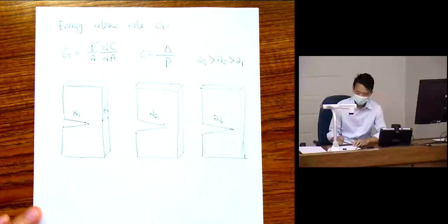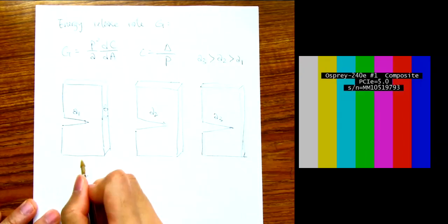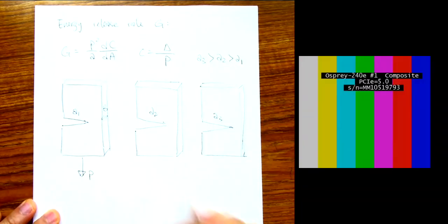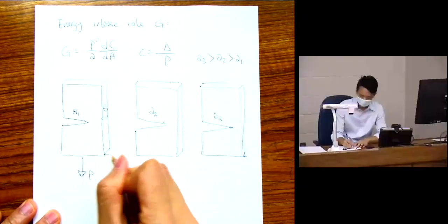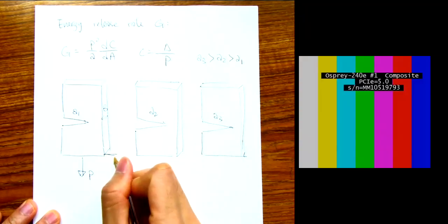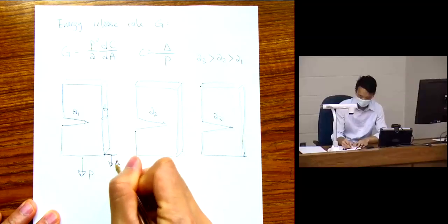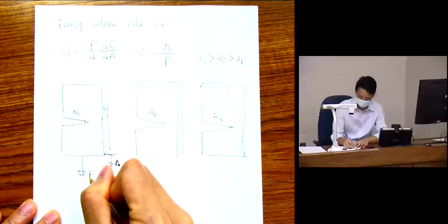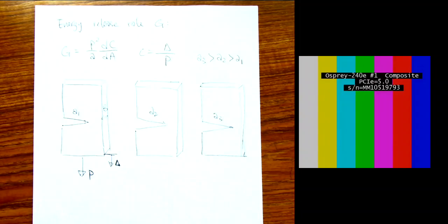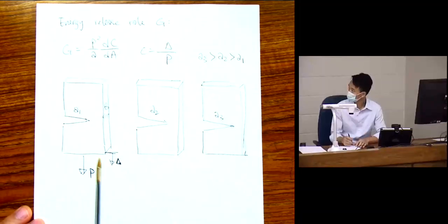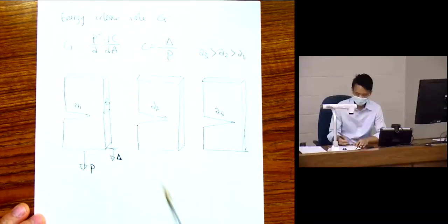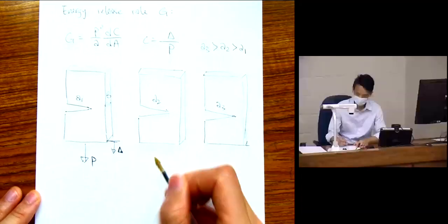So the next thing is that you want to find the compliance, right? So you take a load, you start loading it. You start with 0 and then a small load and so on. And then you measure, corresponding to a particular force P, the displacement. You do the same thing.